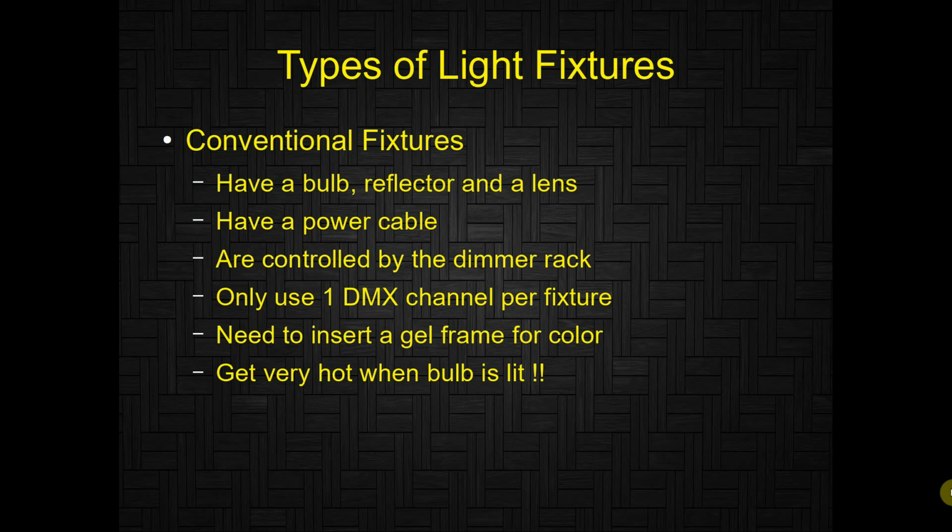One thing I wanted to note is that in these conventional fixtures, you're using somewhere between a 500 watt and a 750 watt bulb. So they get very, very hot. You don't want to touch them unless you absolutely have gloves on. It's one thing you have to be careful of if we are aiming, which I don't think you're going to be involved in, but I know if I'm up actually aiming lights, and they have been used recently and they're on, they're going to be very hot. So I did mention that.